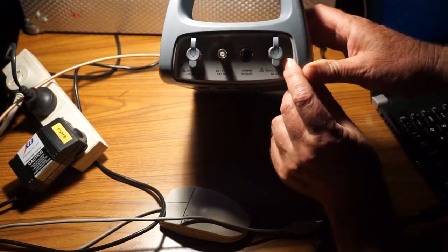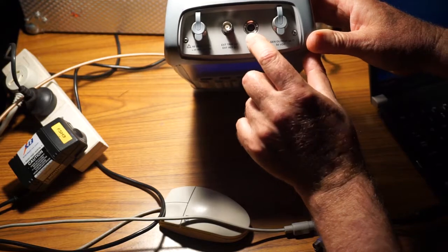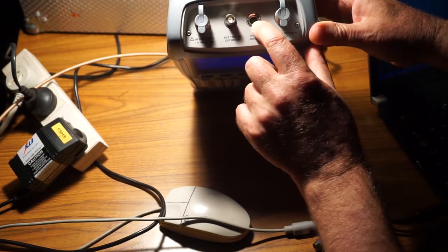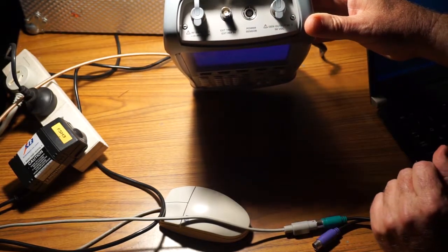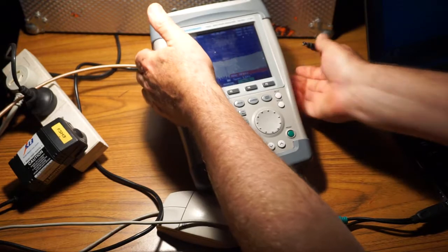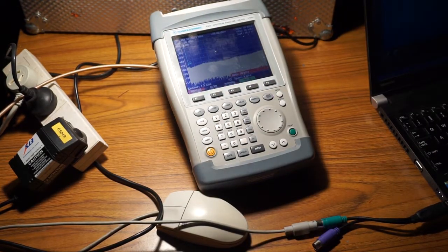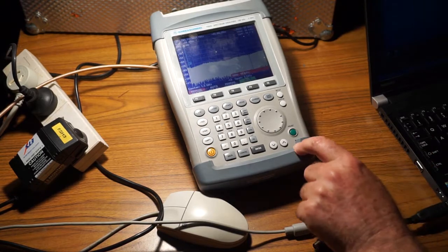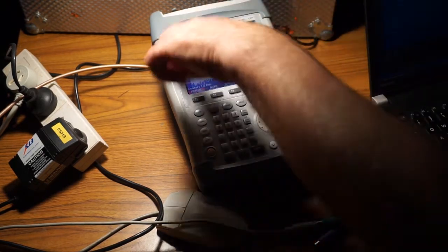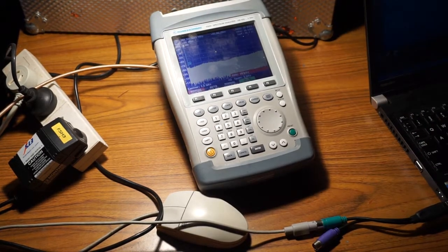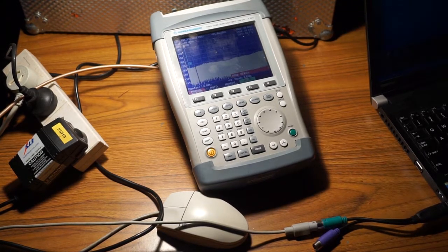And there are other options. There's a strange connector here. There is a thing called a power sensor, another box you can buy that you can plug into this, and it has an RF power sensor in it, and you can feed RF power through it. It uses the processing power of the spectrum analyzer and the display, but it changes the display. It puts big numbers on it, so it will tell you how many watts: 100 watts, 5 kilowatts come on the screen.